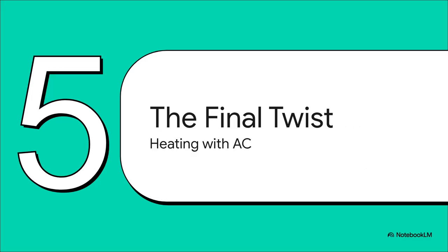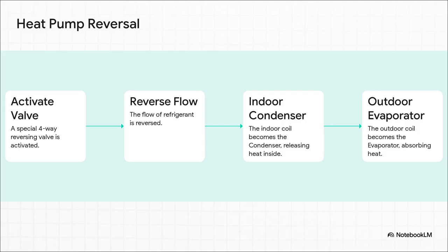All right, section 5, the final twist. So far, we've talked about this amazing system for moving heat from inside to outside. But what if we could flip a switch and run the whole thing backwards? And that, my friends, is what a heat pump does. You add one clever little part called a reversing valve, and it literally reverses the flow of refrigerant.